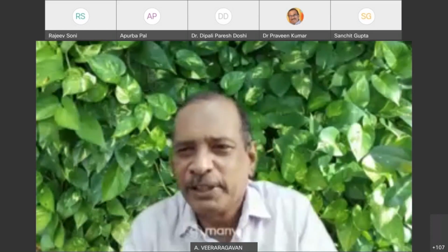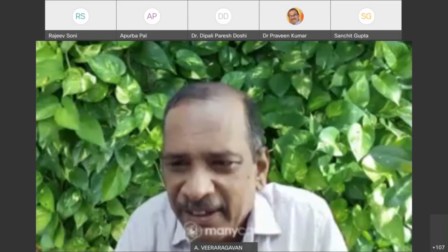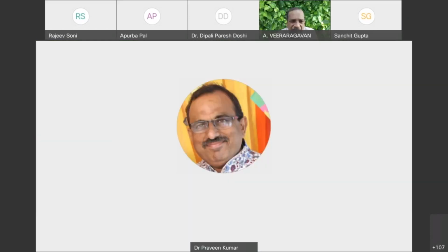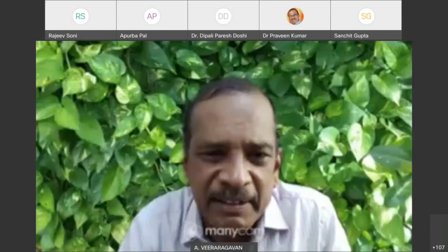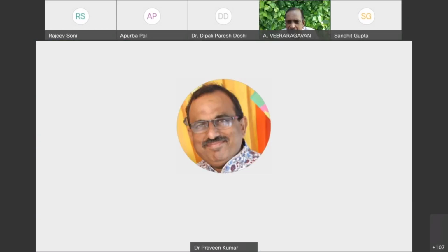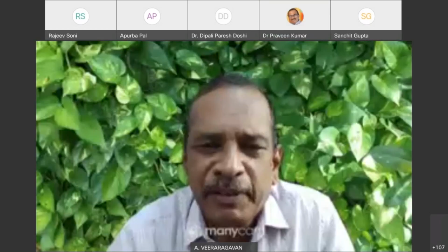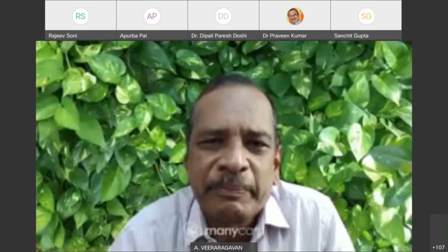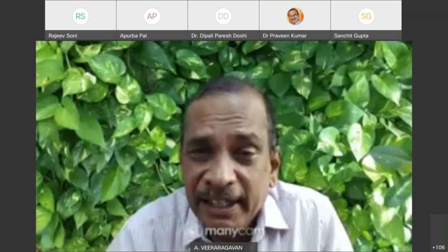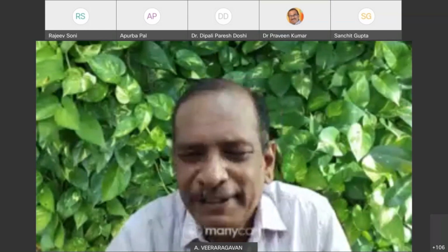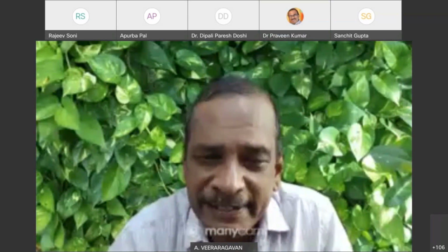Any other questions? I think Sudarshan posed a question. Yes, sir, in chat there is one question: is any pre-treatment required before we provide geotextile fibers? No, it can be taken straight, stretched tight, and then filled. It can be geogrid, it can be anything. I think I did make a mention of that, but because of time limitation, I could not show the other slides.